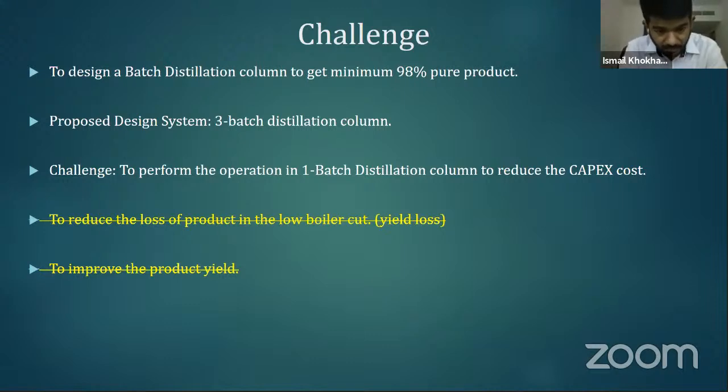So that became the priority rather than designing a distillation column. So before designing, we need to make sure that no such losses were being incorporated. Based on this, we did some experiments, as I told you, and found an entrainer and made sure that the product loss with the impurities cut was reduced.